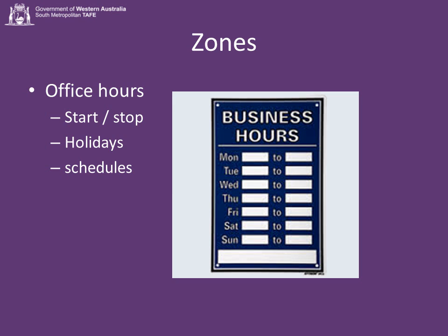Other things to consider when we're controlling. Our air handler is sending out air to zones. These zones switch on or off depending on their schedules. There are going to be start-stops, there are going to be holidays, there are going to be lunch times. By carefully selecting our start-stop times, by carefully setting up our time schedules and our holidays, we can make sure that we don't condition an area when there isn't anybody in it.